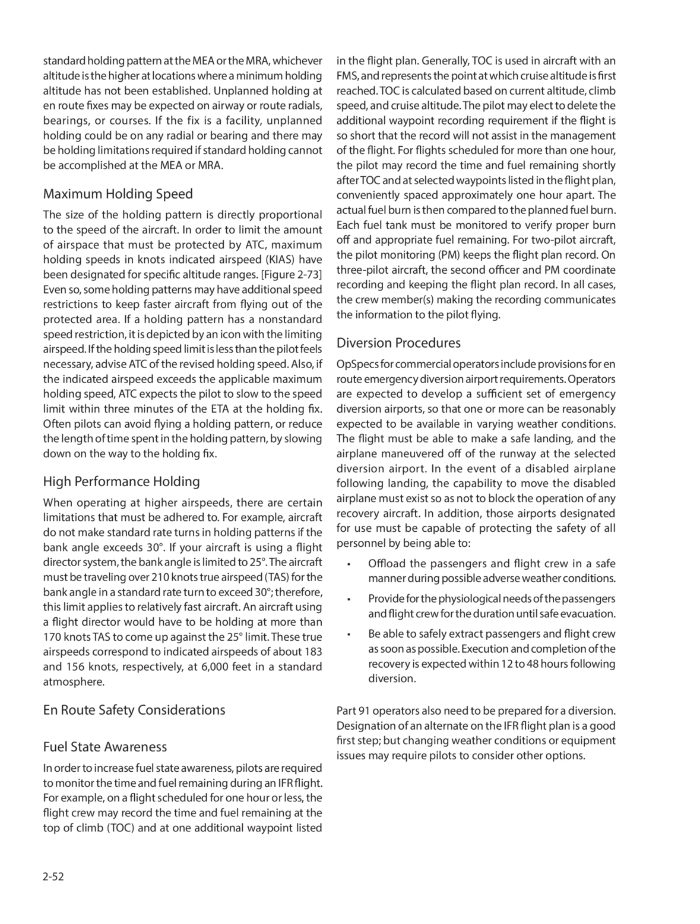En route safety considerations. Fuel state awareness. In order to increase fuel state awareness, pilots are required to monitor the time and fuel remaining during an IFR flight. For example, on a flight scheduled for 1 hour or less, the flight crew may record the time and fuel remaining at the top of climb, TOC, and at one additional waypoint listed in the flight plan. Generally, TOC is used in aircraft with an FMS, and represents the point at which cruise altitude is first reached. TOC is calculated based on current altitude, climb speed, and cruise altitude. The pilot may elect to delete the additional waypoint recording requirement if the flight is so short that the record will not assist in the management of the flight.